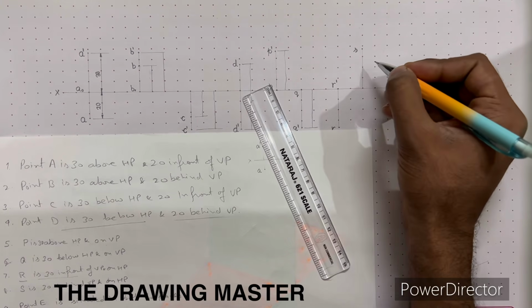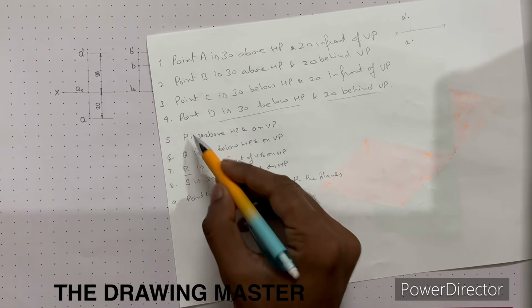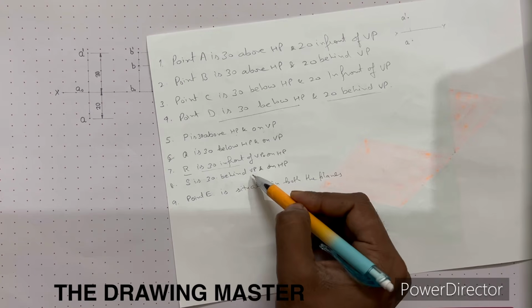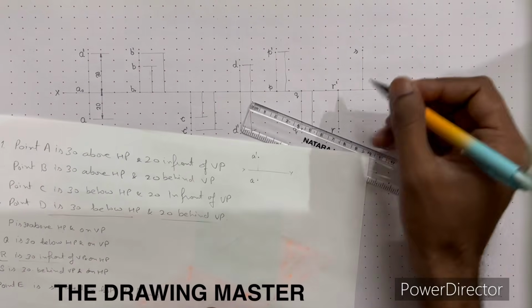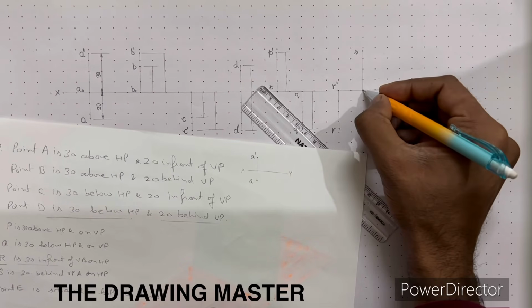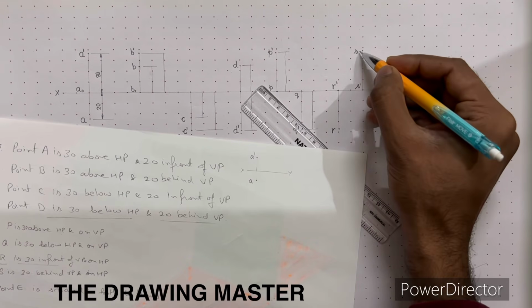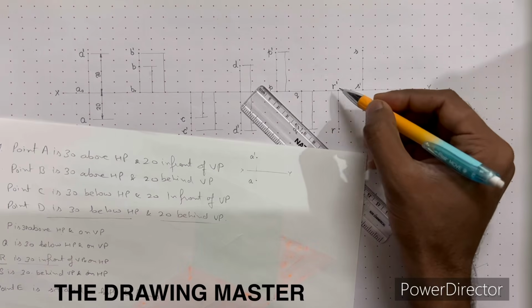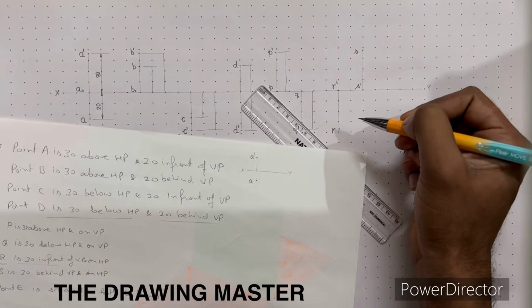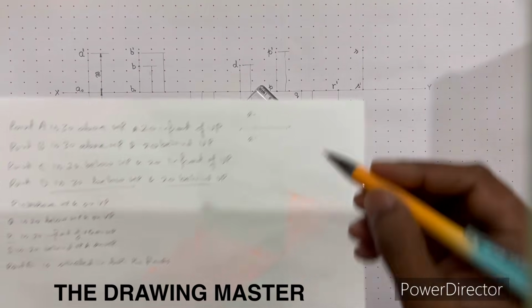Point S is 30 behind VP and on HP. So it is neither above HP nor below HP. So front view will be on reference line, S dash. It is a very simple thing: if this is top, obviously this will be front. If this is front, obviously the second one will be top view. You can write down its dimensioning also.